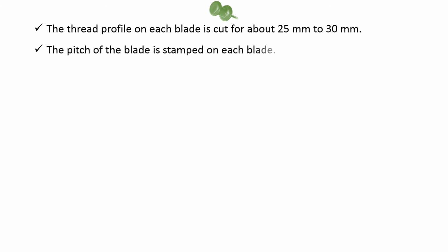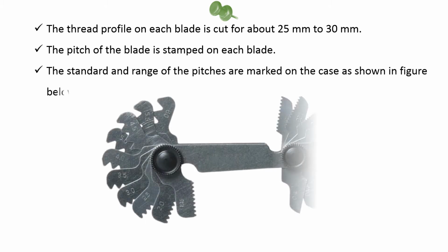The thread profile on each blade is cut for about 25 mm to 30 mm. The pitch of the blade is stamped on each blade. The standard and range of the pitches are marked on the case as shown in figure below.